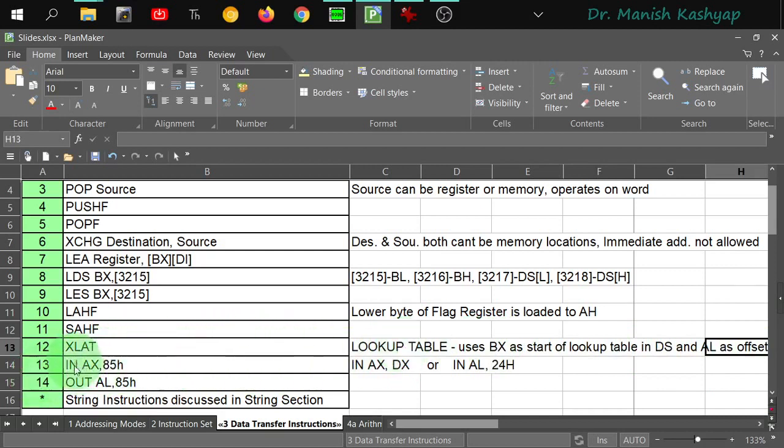After that, you have got the in and out instructions. These are special instructions which I will further elaborate in some laboratory session through some interfacing examples. But as of now, if we talk about the 8085 microprocessor, the data bus there was of 8 bits. So that is why we had 2 raised to the power of 8, that is a total of 256 external devices that can be interfaced to that microprocessor, right?